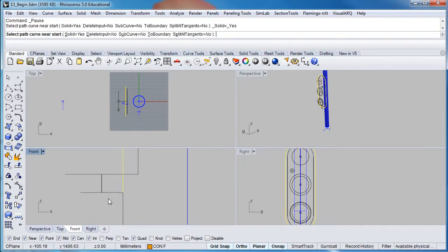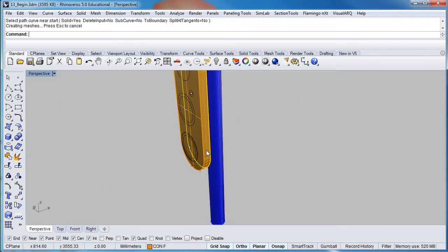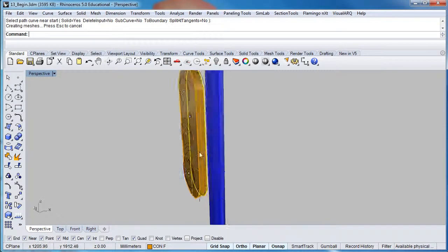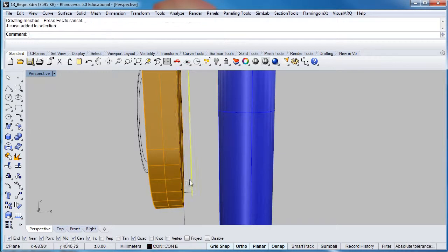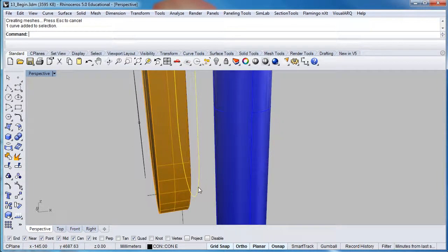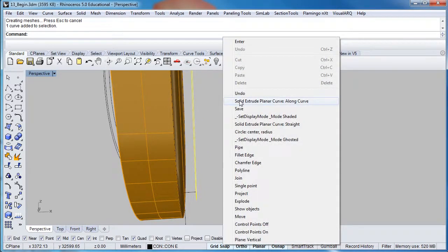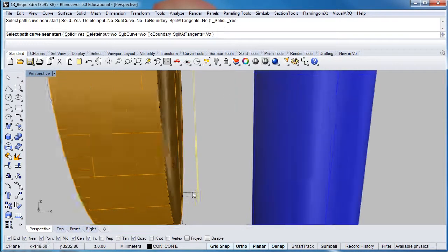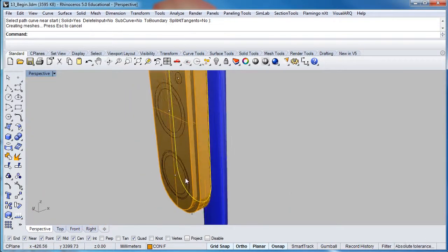So we just right click to bring up the curve again, and this time we're going to click close to the line that we're trying to extrude. And you'll notice it goes in the negative direction, the direction we're trying to achieve. Double click on the perspective view so we can see the geometry we've formed. It's perfectly valid, perfectly good. Okay, now we're going to do it again with the inner curve. So we've made that curve active. This time we'll click on the command bar and we'll extrude a long curve again. And as I said before, we're going to click that construction line close to the line there.